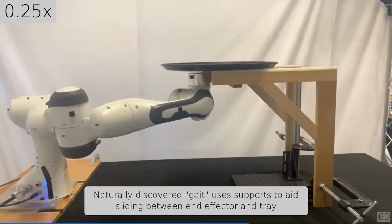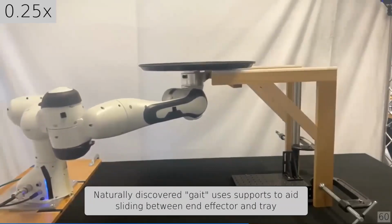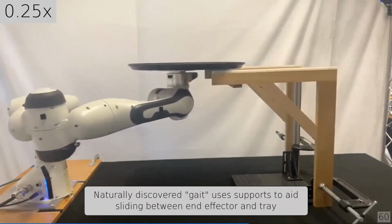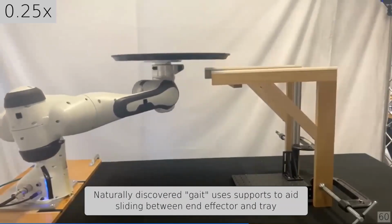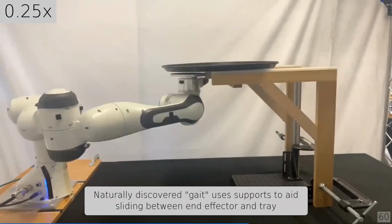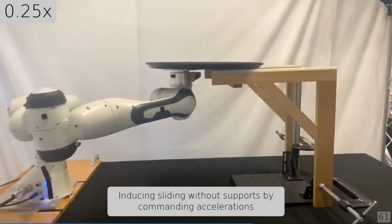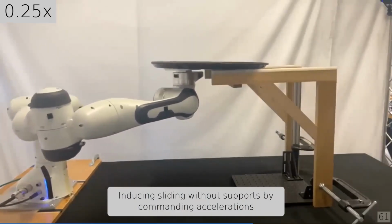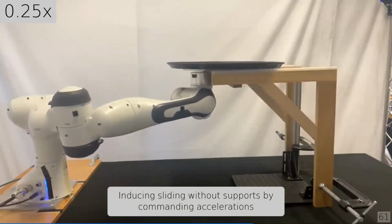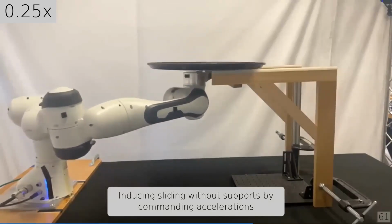By giving just a single target and not doing anything fancy with the reference trajectories, the contact implicit MPC still discovers really interesting motions as well. It really heavily utilizes the supports to aid in repositioning here. And I want to emphasize that this really is indeed dynamic sliding. In the very beginning, at the top of this, it's able to slide the tray on the end effector without even using the supports, right? It's sliding the tray forward before it even touches the supports.